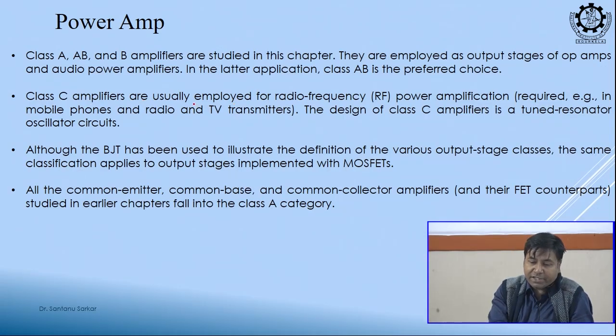Class C amplifiers are generally used in radio frequency amplification. For example, they are used in mobile phones, radio and TV transmitters. So, all your mobile phones have class C type power amplifiers. They use a tuned resonator oscillator circuit, the tank circuit that we studied in the oscillator, and those kinds of tank circuits are used at the load.